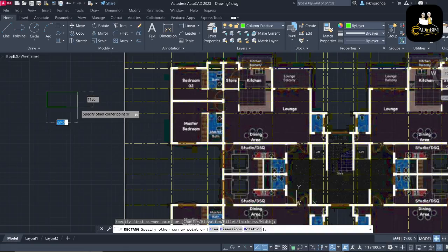I can simply write, so this building, let's give it 300 by 200. Okay. But I want to do this up to the 12th floor. 300 will not be sufficient. We can use 300 by 450.